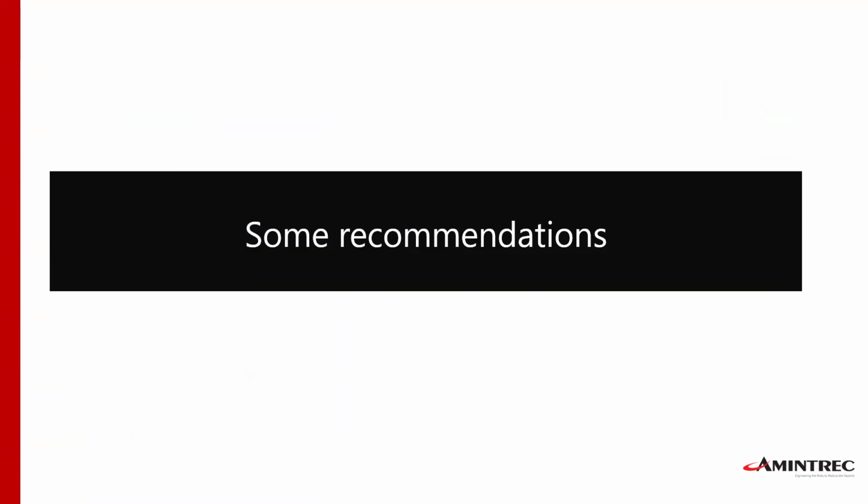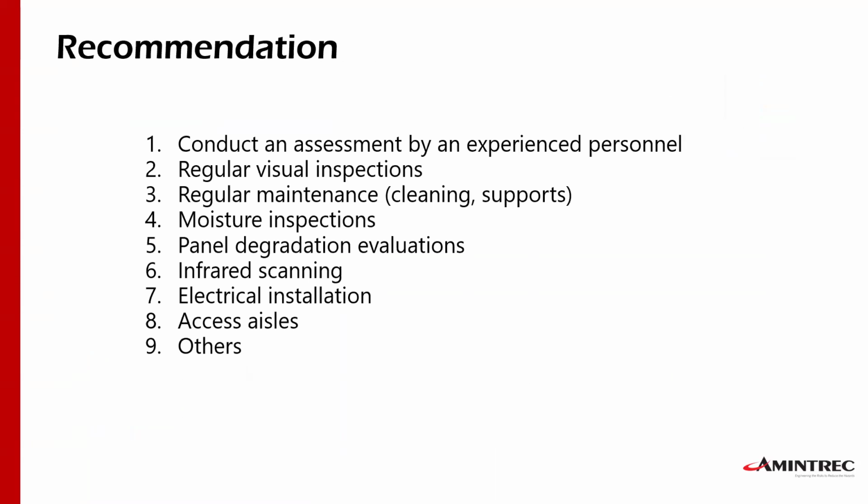Now, some recommendations to keep in mind, just to decrease the number of losses for photovoltaic panels. One is to conduct an assessment by experienced personnel. Regular visual inspections, not just to identify if the panels are damaged, but also if there is something that will block the panels and create a shadow effect or shading. Regular maintenance, cleaning. All the panels have to be cleaned regularly.